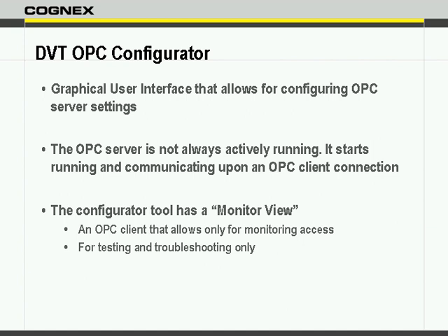So again, the OPC configurator is a graphical user interface that you use to configure the server settings. The OPC server, like I mentioned, is not always actively running. It starts communicating upon an OPC client connection. And we'll see later on that the configurator tool has a monitor view. This monitor view is basically an OPC client, but an OPC client that only allows monitoring access to the OPC server. That way, you can test and troubleshoot your settings from the same OPC configurator utility.